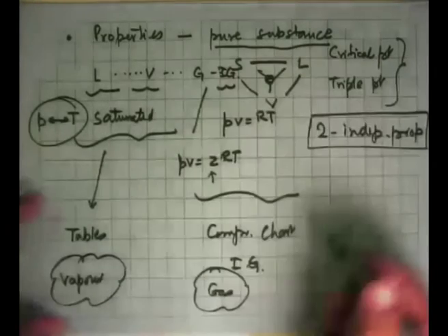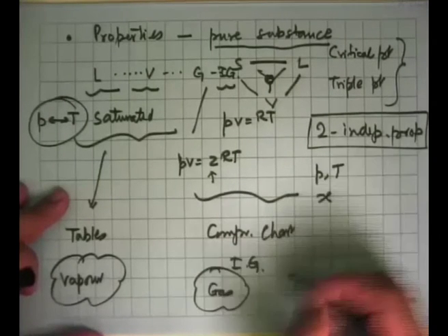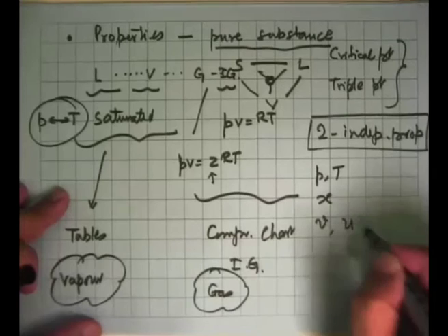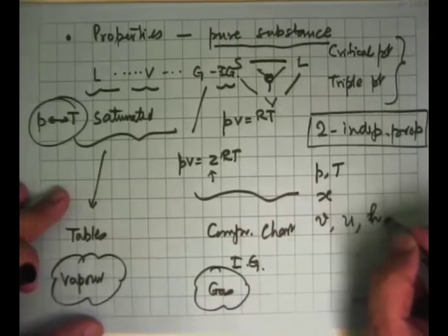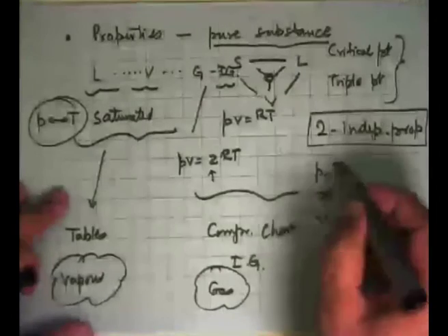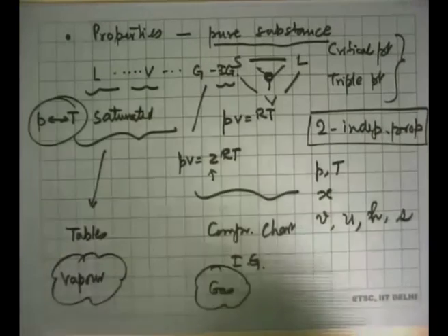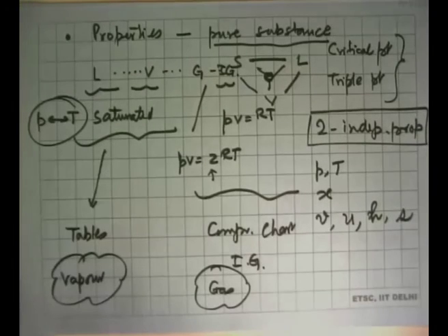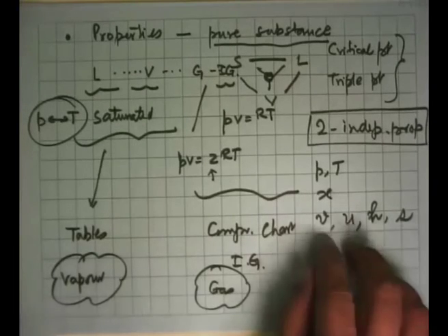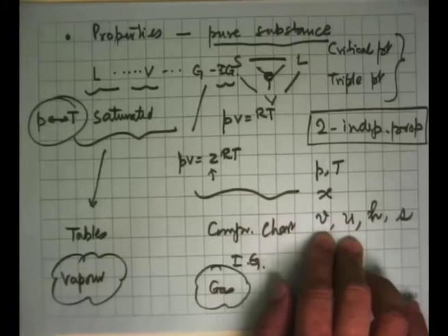And then we came across a whole bunch of properties here: pressure, temperature to begin with, then dryness fraction, specific volume, specific internal energy, specific enthalpy, specific entropy. In a saturated state, pressure and temperature are not independent, but any two of these will always completely specify the state. In solving problems, somewhere we got V and U, and we said, okay, now I know the state is fully specified and I can calculate the others.